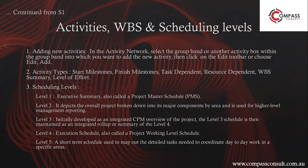Yes. See, mostly we'll consider the same one, and whatever the set of WBS we are creating in Primavera, it will be considered as the levels, like the root project. We consider the first level, and whatever the number of sub WBS and hierarchy of WBS we are going to create, it will be considered as level 2, level 3, or level 4.